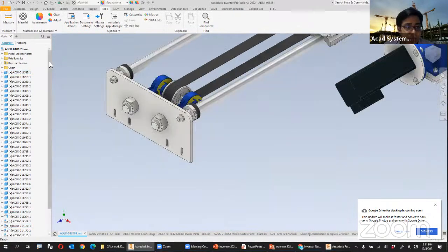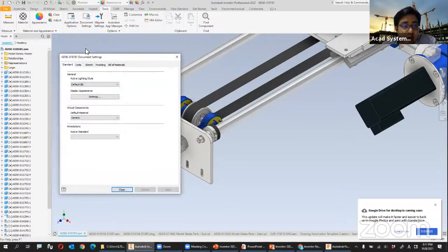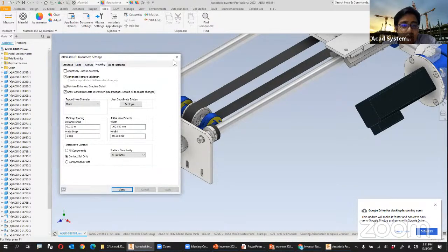Now, the other thing is that sometimes when you try to input, they have some dash line instead of circles. That is actually because the part is not able to compute the constraint status. So what you can do is refresh back. Before we refresh back, there are other ways we can use. One is in the document setting on the modeler, where you can turn this on.